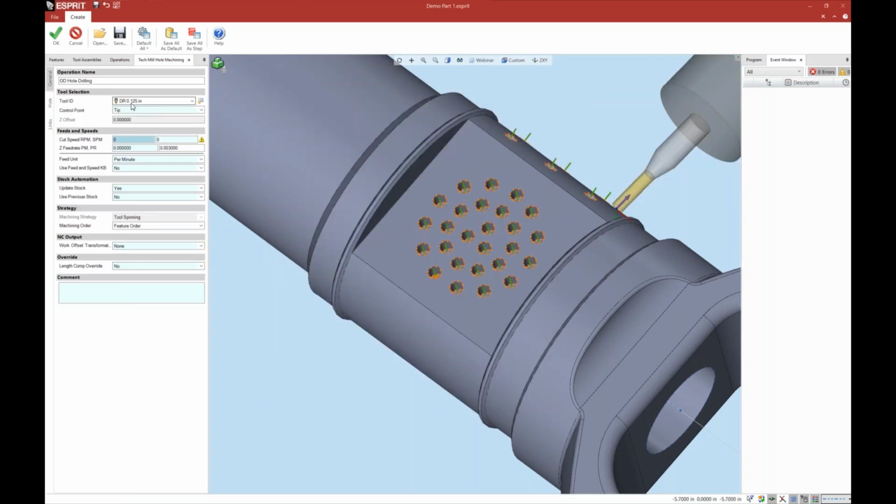And now my drill tool is updated to match the feature diameter. So once I go through my operation here and I put in a couple expressions, I'm going to do one here for grabbing the tool. I'm also going to create an expression for setting a PEC increment based on the tool size.